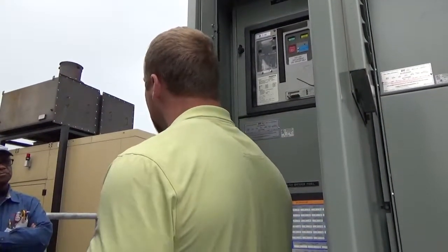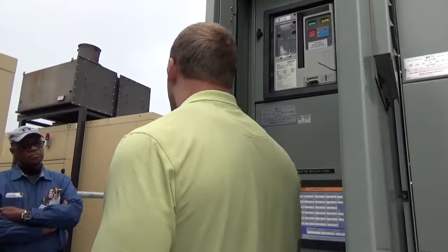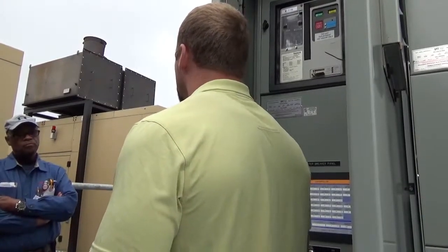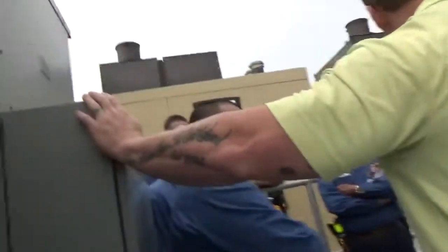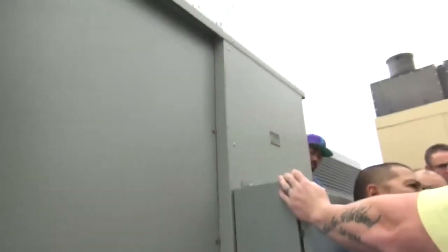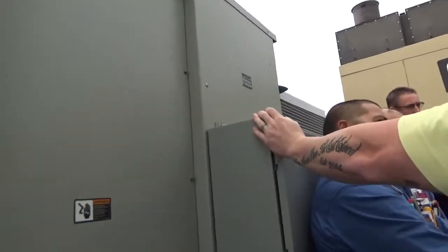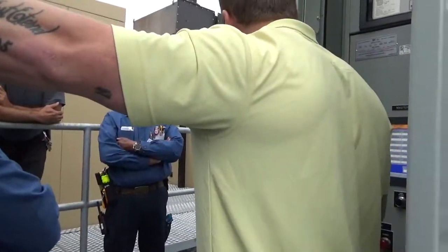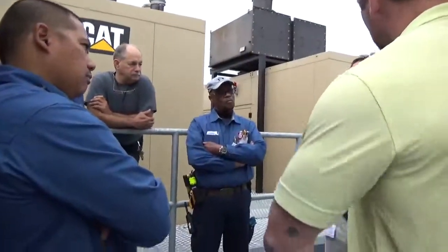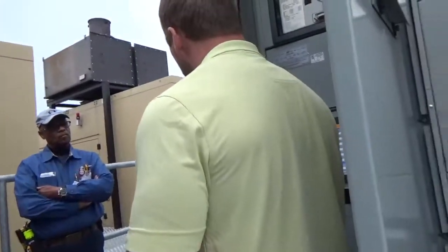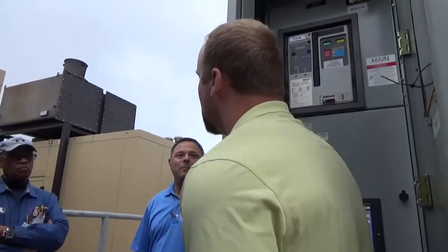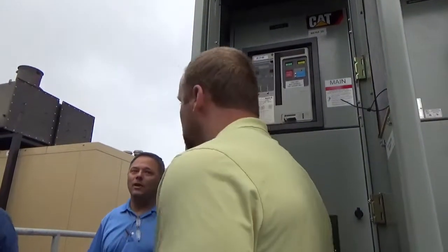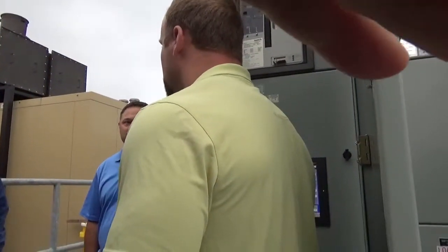Okay. So that's nice. I'll need to ask about that. Yeah, I would ask, if that's how they want to use it, because then that way you don't necessarily always have to use the load bank to offset that. What is your total rated site load? No one knows yet. It's an issue I'm having with Red Top, Mr. Chuck. No one knows. So we just rolled all transfer switches and we had literally 180 amps and it was nothing. We barely got 20% on one generator. Okay. Of all of them. So we're gonna load bank no matter what. Even with 1 gen, yeah.